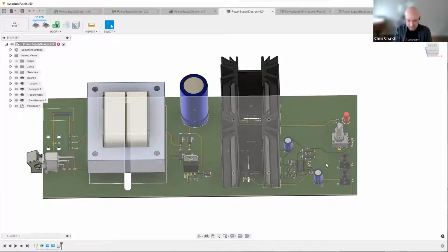Because I'm noticing we don't have really any test points. I did have the opportunity to look at this design earlier, so I noticed we don't have any test points anywhere. So thinking about how we would test this device, I'm noticing there's a very small amount of SMT. If this was an SMT heavy board, a lot of digital logic, we would use something like in-circuit test or flying probe. And with the in-circuit test, it's a little less flexible than flying probe because what we would use is a fixture that's kind of set in one design, but that's in line in the SMT process. So we want to make that as easy and as cost effective as to do.